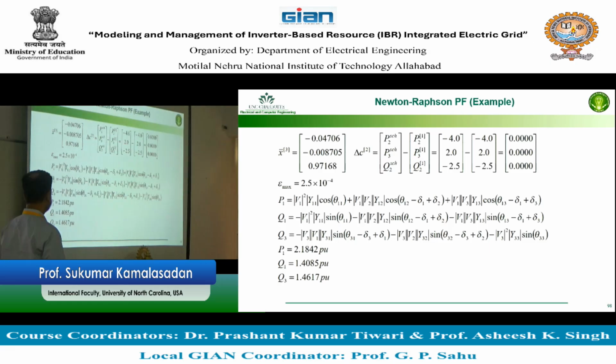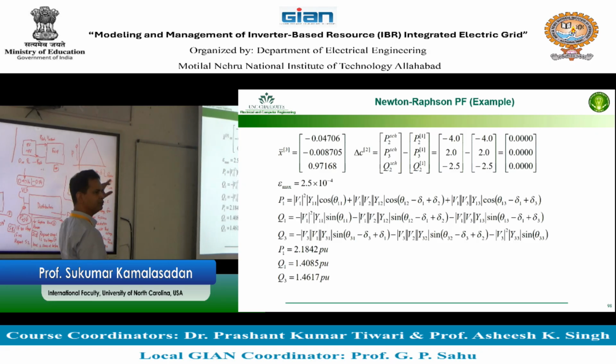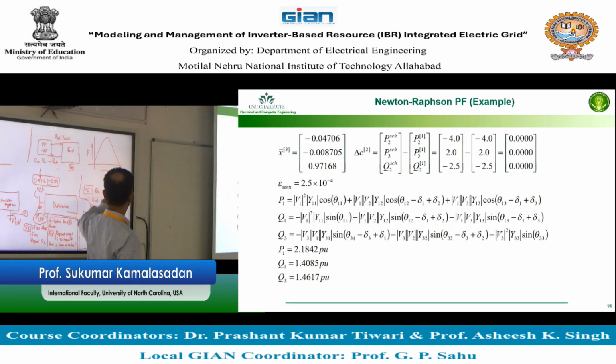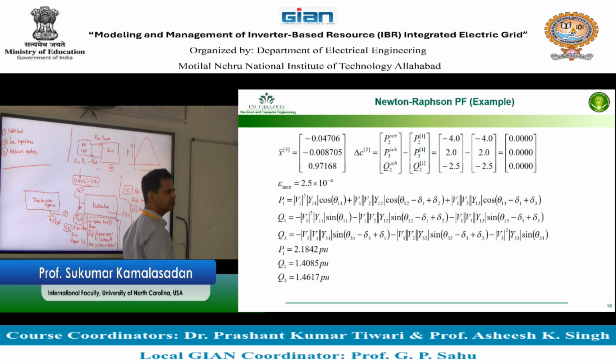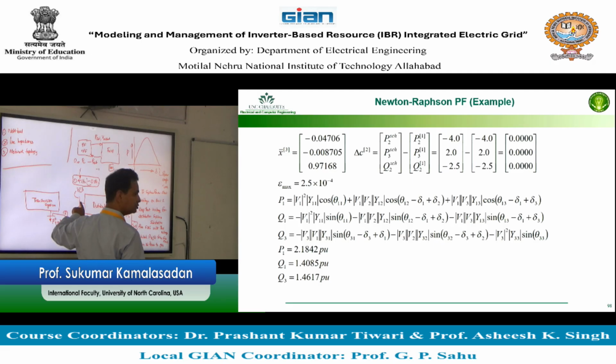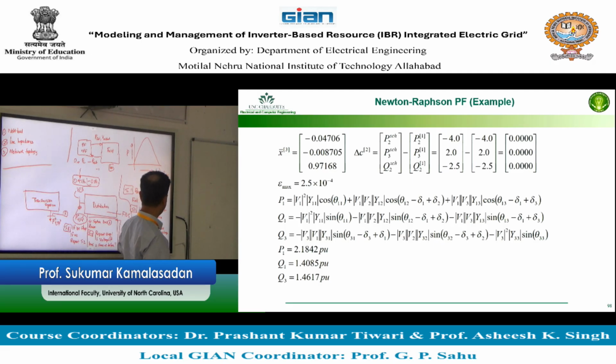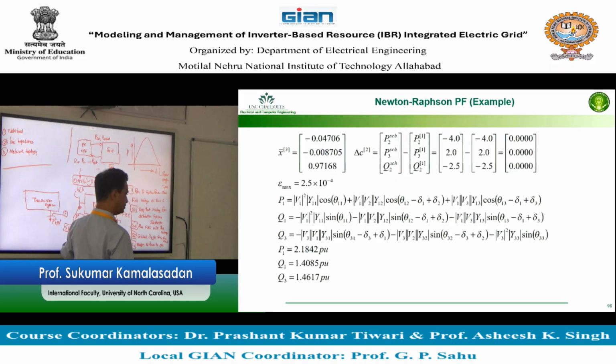Okay, I'm going to repeat it. Step number 1, if you cannot read my handwriting, you can also see. Run transmission system power flow. Find voltage on bus 2. Step number 2, keep that voltage for the distribution system substation, which is this. Run forward backward sweep with this voltage in the distribution system substation. Calculate the P plus jQ from the substation, from the forward backward sweep. Multiply the power to get the transmission system bus 3 power.